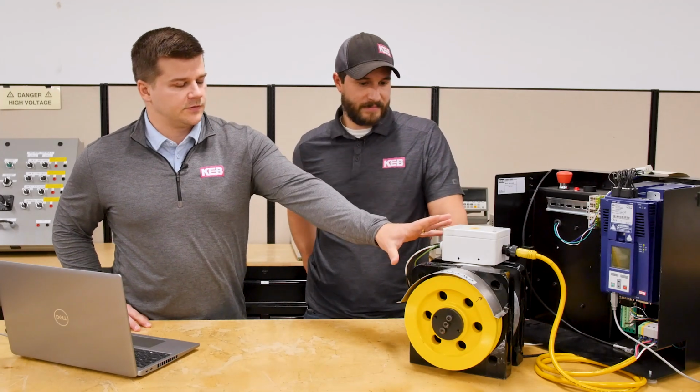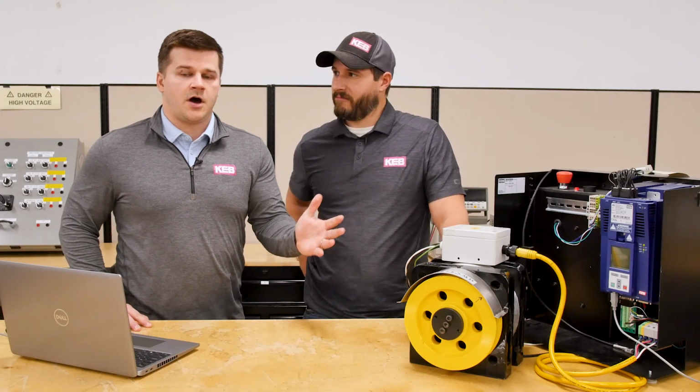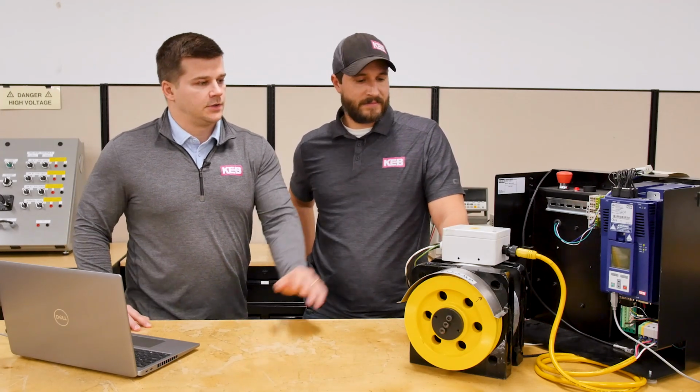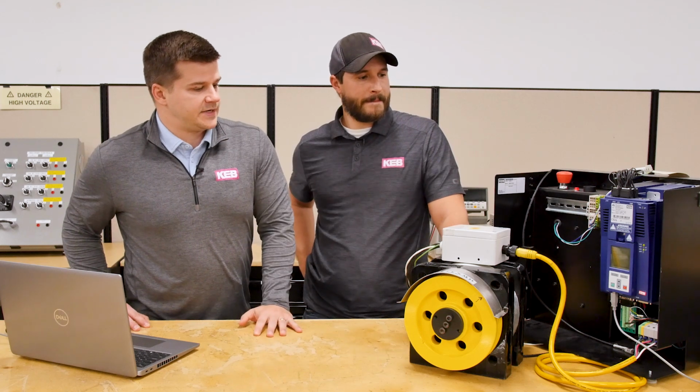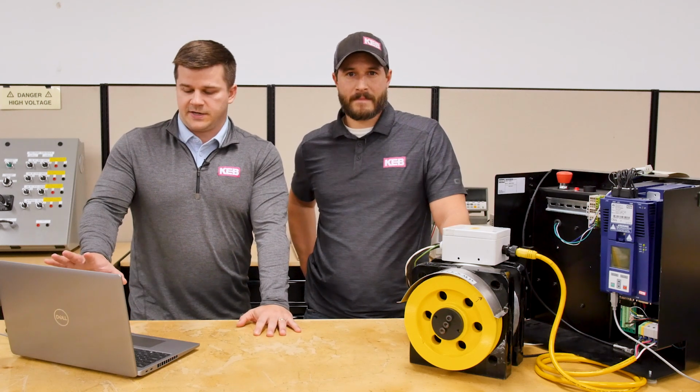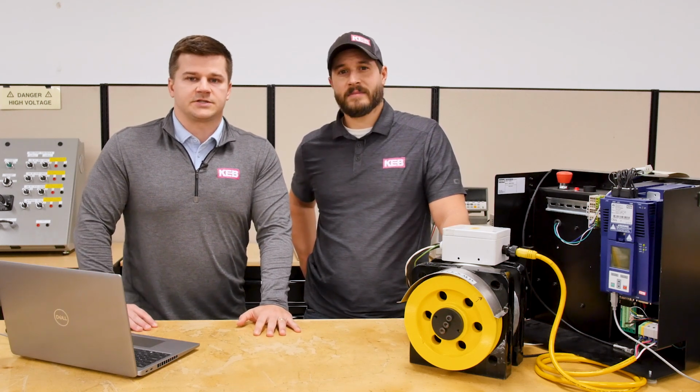So Mike, tell us a little bit about the setup here, starting with the hardware and then the software. We've got a high pole servo motor here. This would be often used in elevator applications. We've got our F6 VFD connected to the motor, and then connected to the drive, we've got our CombiVis 6 software. Next, I'm wondering about what encoder offset is. Can you explain that a little more?